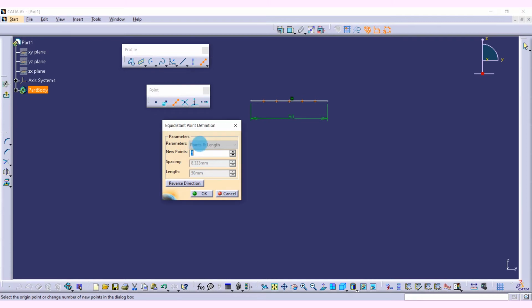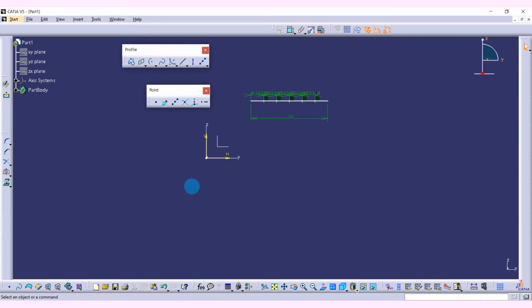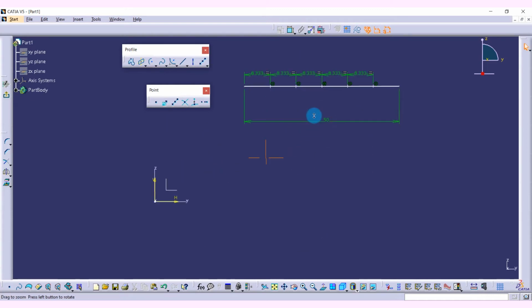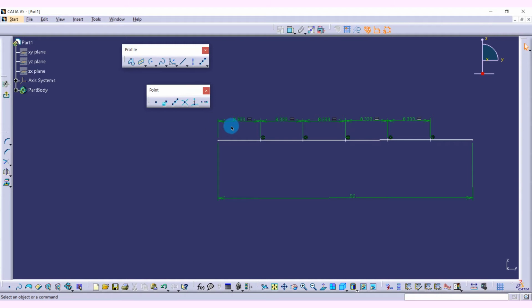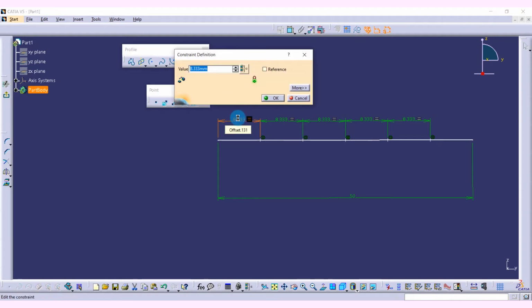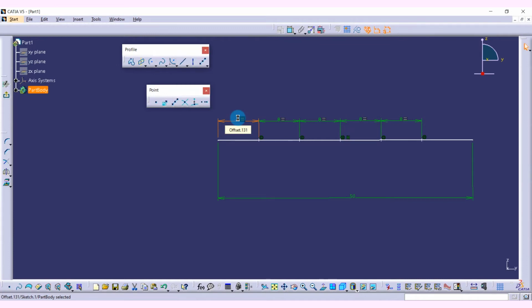Wherever we see the gray in color, it means no other options are available or it is not active. And if click OK, the system computes with the dimensions, and we can change the dimension values and it will update appropriately. So all will change. There is a relationship between each dimension, and we can key and change it. This is all about point creation on a curve.